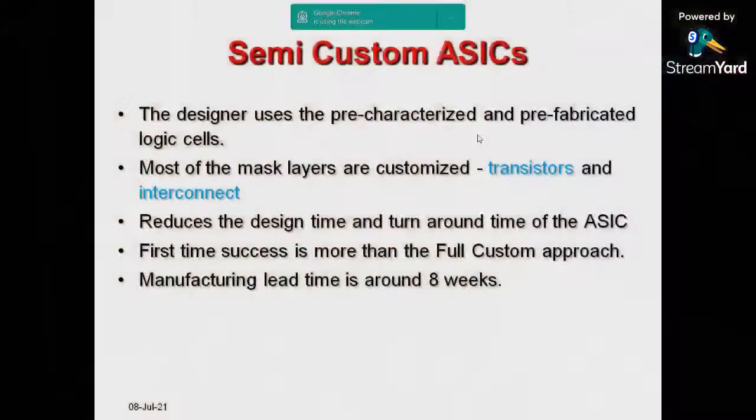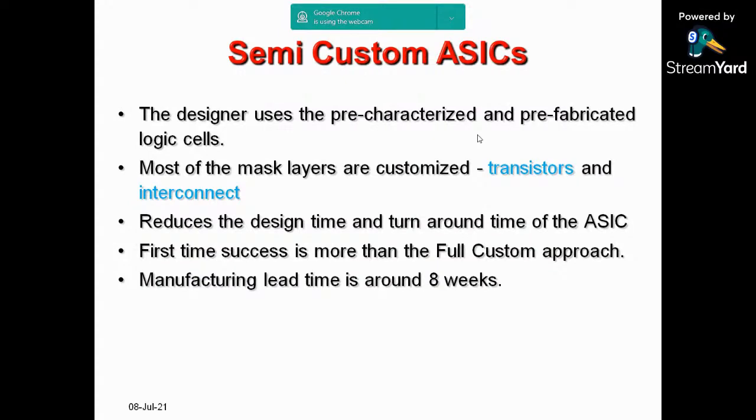So you start by writing, you might have studied about hardware description language. That is a language built to describe hardware. You might have studied Verilog and VHDL. If not, you definitely will be studying. It is a language designed to build digital, and even analog, blocks. You can write Verilog or VHDL and feed that code to the tool, and the tool will pick up the cells necessary for the code you have written. You can arrange the cells, I'll show you in the next slides, interconnect them, get the mask information from that, and give it to the fabrication people.